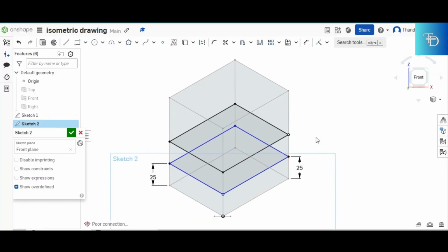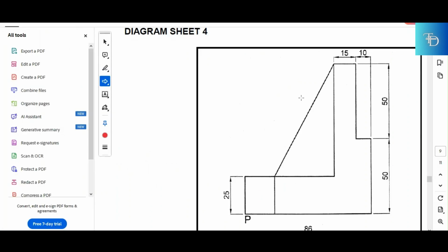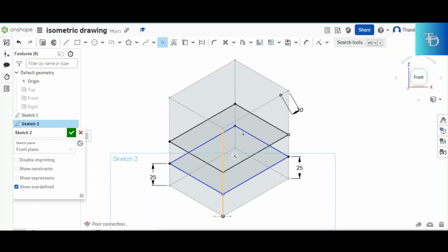So you head back to your cube right there. This is the front. This line right there is that point right there. You pull up your ruler, you go inside by 10 millimeters, and then you go inside by 15, and you mark the 15 from your 10 millimeter. You don't mark your 15 from scratch, because that is what the question is saying. The question says you go inside by 10, and then from the 10 you measure the 15. You follow the dimension, you follow what they are saying. So now we've already marked our 10, so the next thing is we mark our 15.